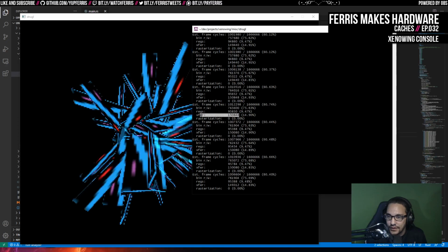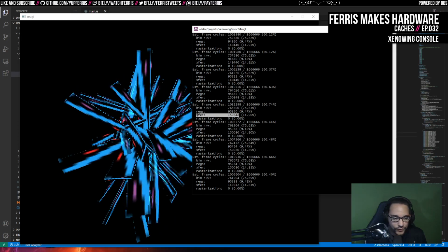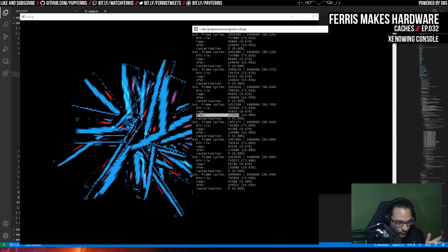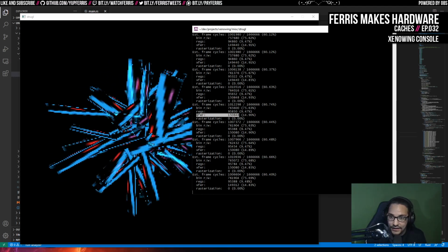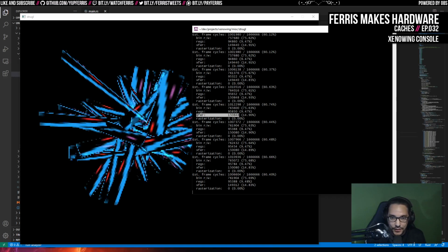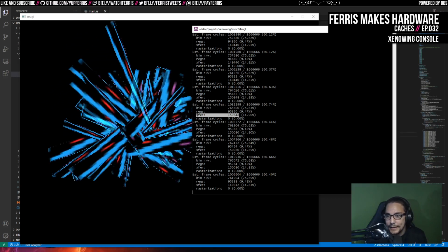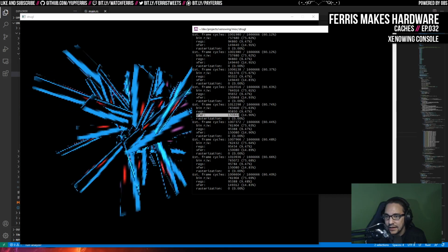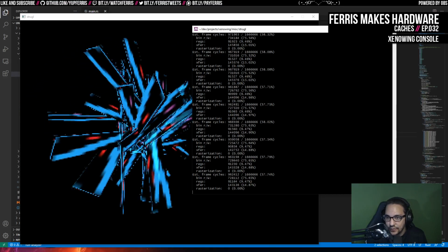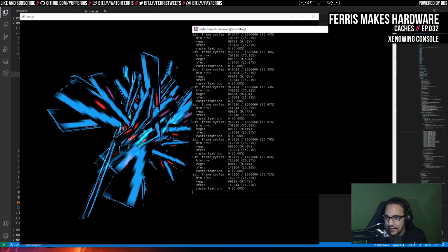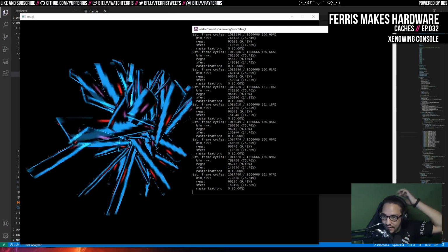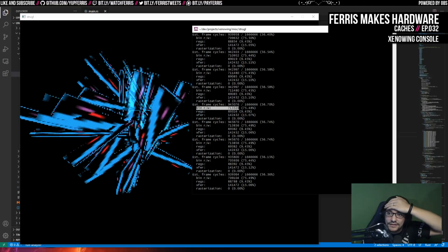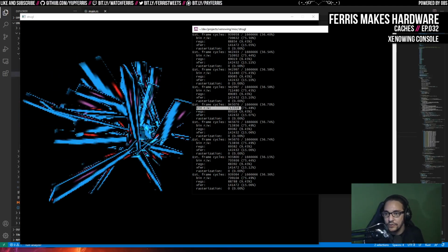This xver number is how much time we spend moving data in and out of the rasterizer. So either if we're moving in color data or depth data or moving those out, or if we're moving in the texture cache, which is explicitly populated in this architecture currently, all that gets added here. And that's just an estimate, but I think that's a pretty good estimate. Whereas this regs one, I think, is a bit on the low end because my CPU kind of sucks right now. And then, oh no, actually it looks like, no, this is something else. Yeah, so that last one is this bin read and write.